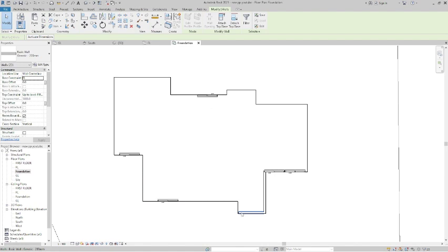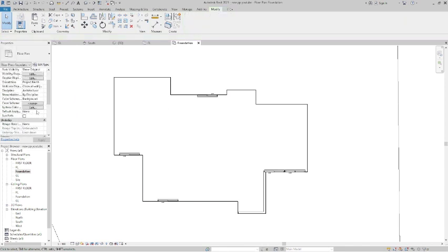So now we don't have it here. So we can draw the foundation, but before we draw the foundation, you have to change the range. So I'll click somewhere here, empty space. I'll go to my project property, go to range base level here, range base underlay. So range base level is none. So I'll change it to what? Final floor. Apply.